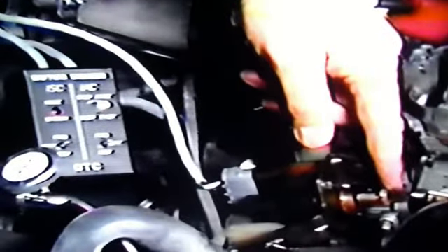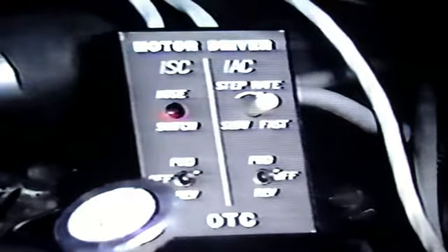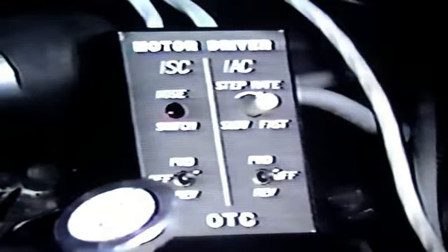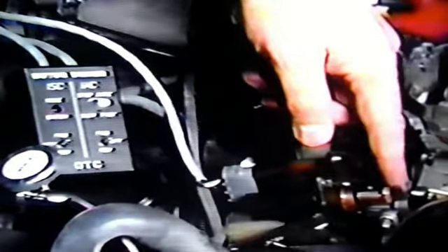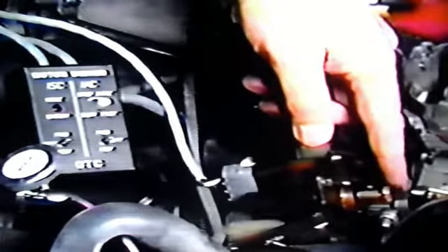To do an ISC adjustment, we go to the idle speed control motor, which has 4 connectors, and hook the test lead to terminals C and D, the 2 closest to the motor. Using this tester, we then push on the nose switch and get a red signal light that tells us the ISC throttle contact switch is operating. You could do this test using jumper wires, but it's definitely worth the investment in a factory rig.